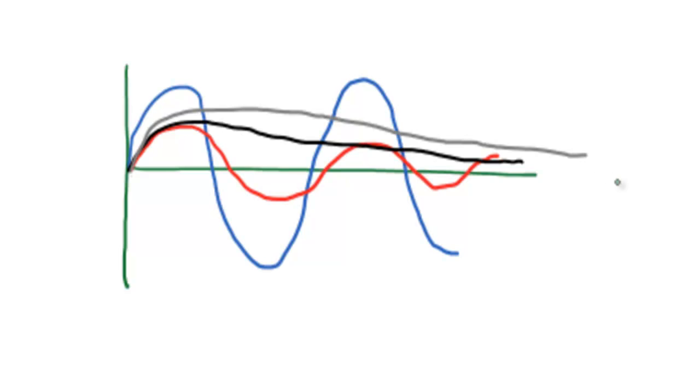That means if you want to commutate the thyristor in case of load commutation, the load must be either undamped or underdamped. Based on this conclusion, to turn off the conducting thyristor in a class A commutation circuit, the load must be either an undamped or underdamped system.